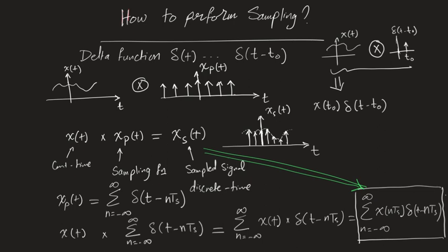Okay, good so far. Now up to this point, we know how to perform the sampling operation. How can I take samples from a continuous time signal to produce some discrete time signal? And we have also the mathematical expressions for everything. The original signal itself, of course, can be anything, and then the continuous time. And then the sampling function is written as a train of deltas. Those trains of deltas are multiplied by the continuous time signal to produce eventually a discrete time signal that is still a train of deltas, but instead of all of them having the same magnitude now, they are picking the samples of x of t at the locations of the delta.